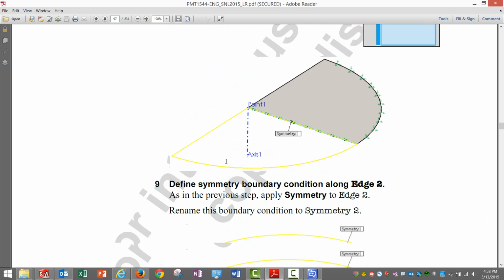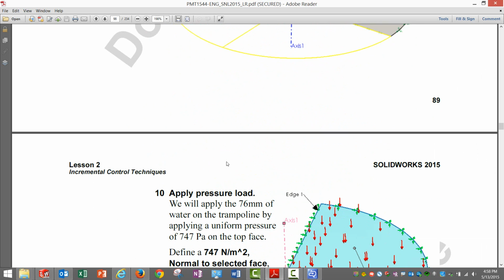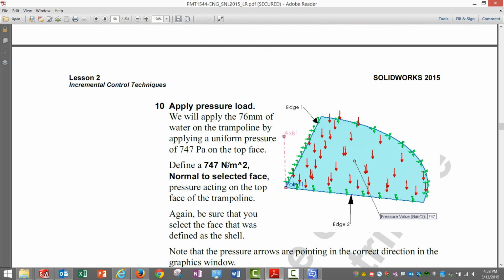This also tells us that we need to move to nonlinear analysis. This is a kind of geometric nonlinearity wherein a huge amount of deflection is observed, and we are not accounting for change in the stiffness over a period of time.